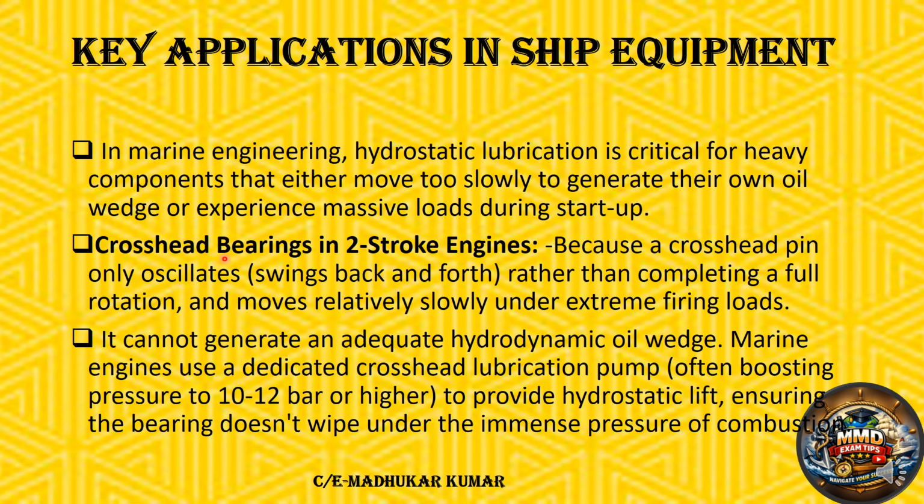So, crosshead bearings in two-stroke engines. The crosshead pin only oscillates, swinging back and forth. So the movement is back and forth, rather than completing a full rotation, and it moves relatively slowly under the extreme firing loads. So the combustion is there. You can see how much pressure is on top of the piston. We know the peak pressure and all. So the separation is required. It cannot generate an adequate hydrodynamic oil wedge in the case of hydrodynamic lubrication.